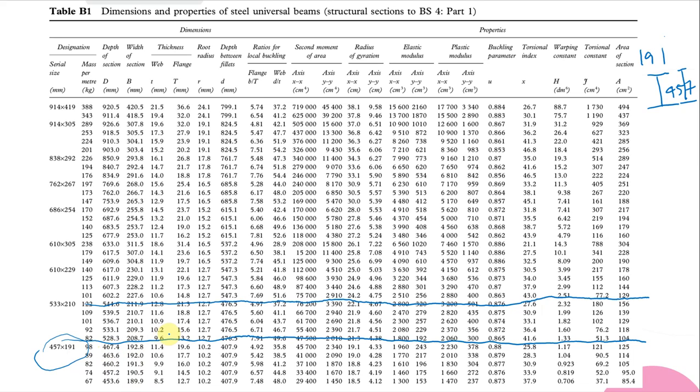So, it is easier. You wouldn't want to buy a beam where the depth of section is 460.2, B is 191.3, web thickness is 9.9. We don't do that. We just read the serial size here. So, we will know which beam we want to use or buy, because it is easier to label and easier to memorize, and much easier if we have the family. It means they are grouped together in one family, one series. It is easier to refer to. Okay.